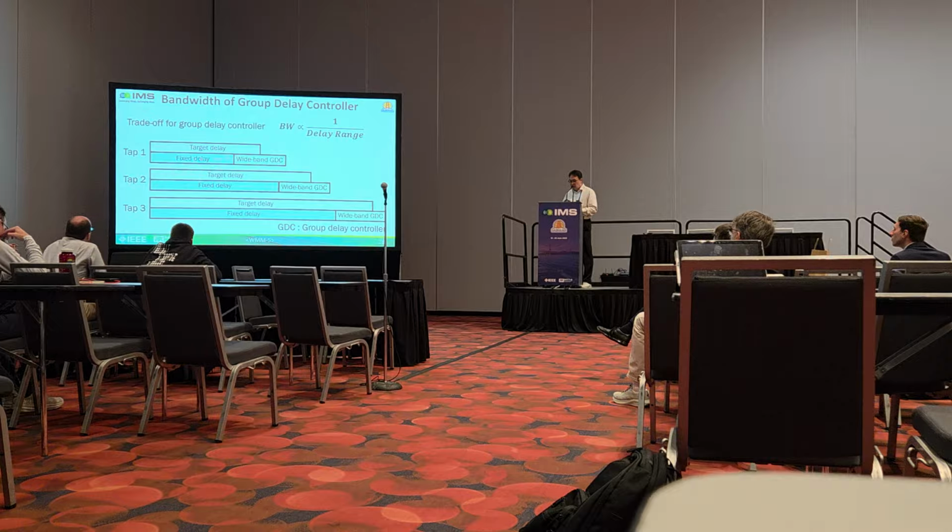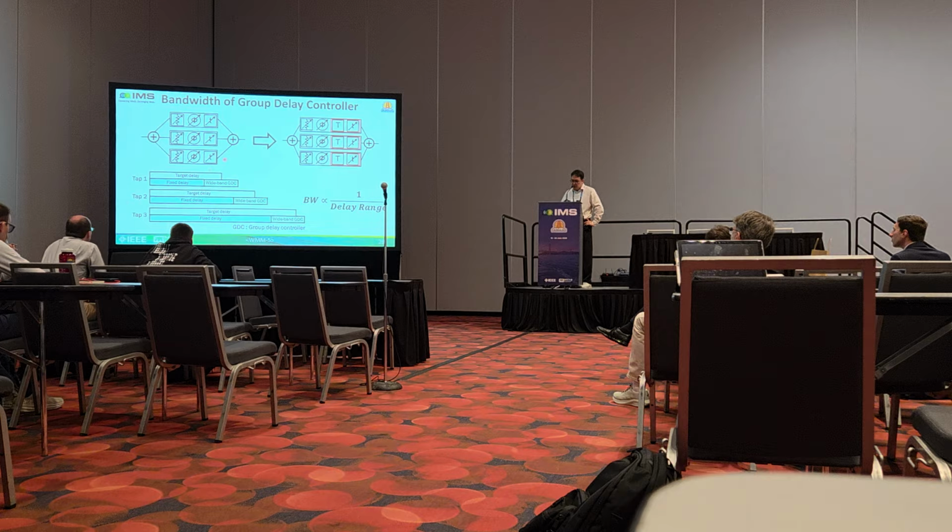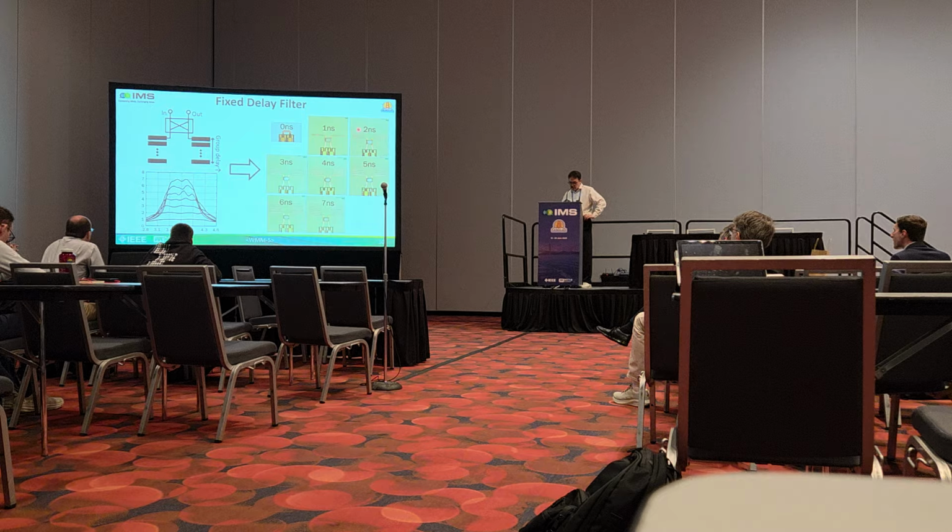So adding fixed delay and wideband group delay controller together, we can achieve wider bandwidth. This is the first design, and we changed this group delay controller to fixed delay and group delay together. And the fixed delay filter looks like this. By using a coupled line, input to output delay can be designed. So fixed delay is designed from 1 nanosecond to 7 nanosecond.